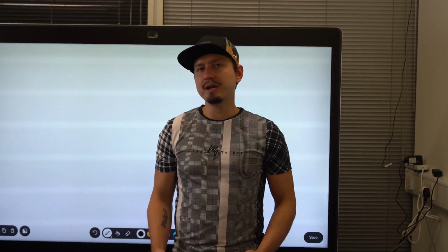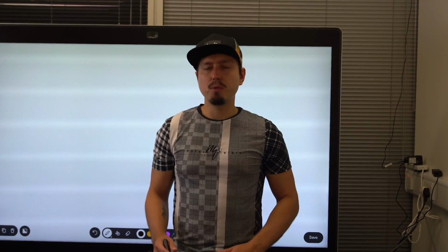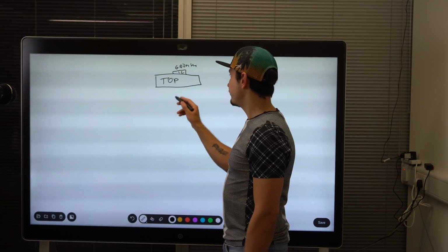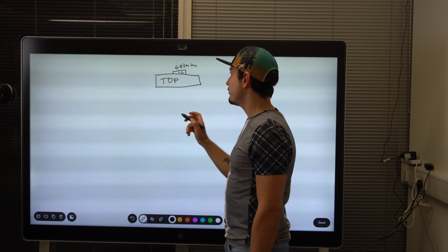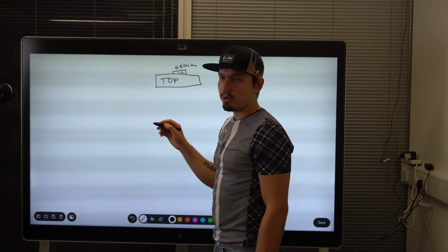Then we're finally ready to begin the PCB layout. And with PCB layout I always start with a layer stackup, because I want to make sure that every high frequency layer has an adjacent reference plane underneath it, and I want to have it no more than 4 mils apart. So it will have some sort of IC, maybe an IMX microcontroller with 600 MHz clock frequency.